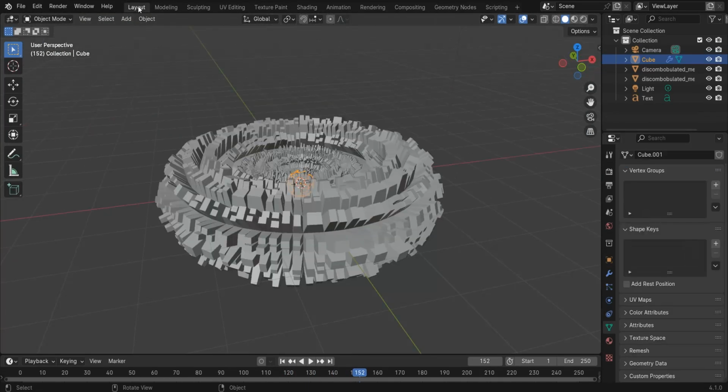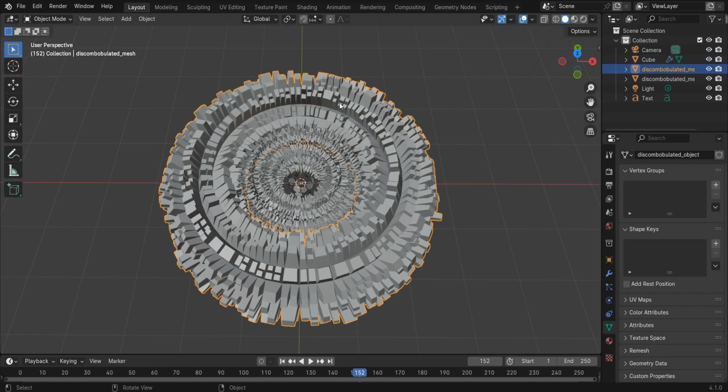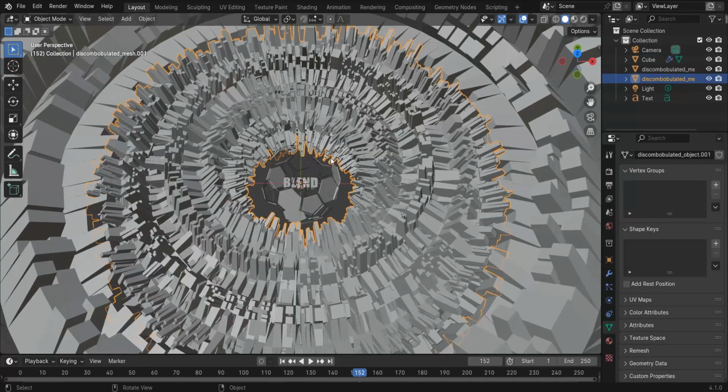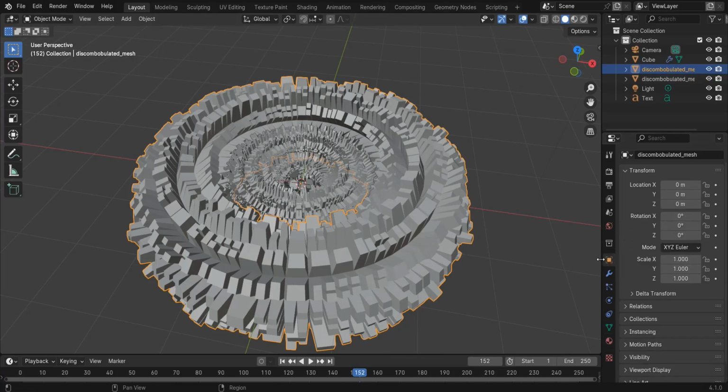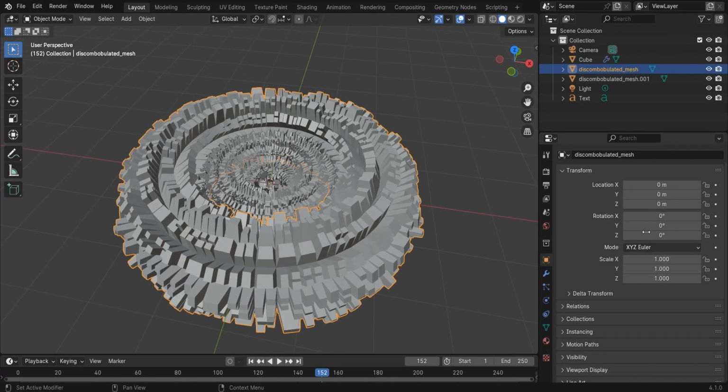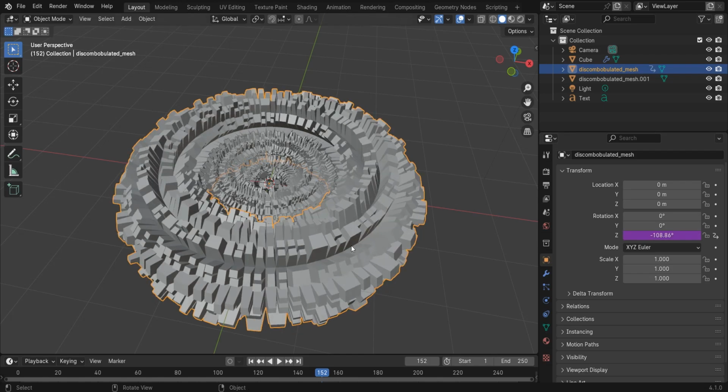Now let's go back to the layout, and before we add materials to our objects, let's animate the objects we created with the help of drivers and keyframes. I select this object first, go to Object Properties, and click on Z Rotation and type #frame/-80.